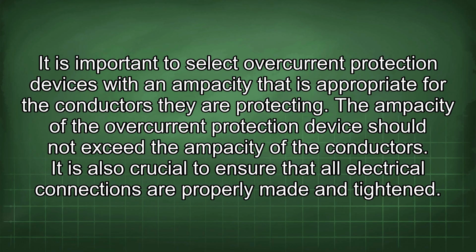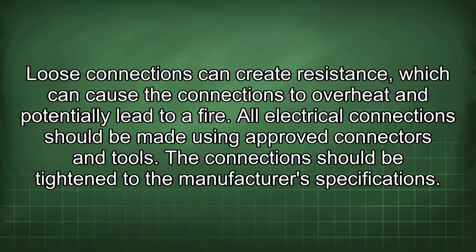It is also crucial to ensure that all electrical connections are properly made and tightened. Loose connections can create resistance, which can cause the connections to overheat and potentially lead to a fire. All electrical connections should be made using approved connectors and tools. The connections should be tightened to the manufacturer's specifications.